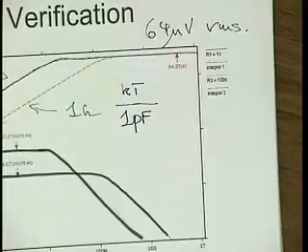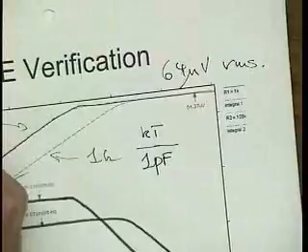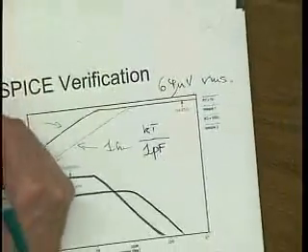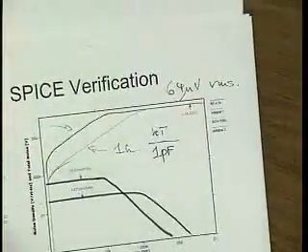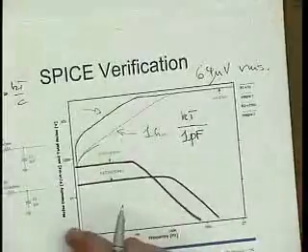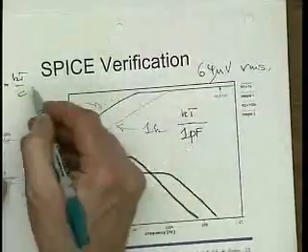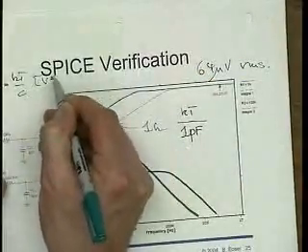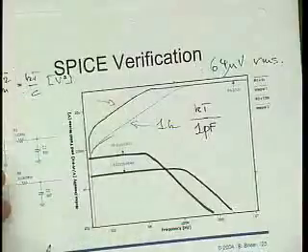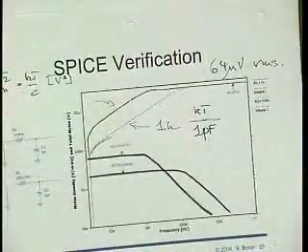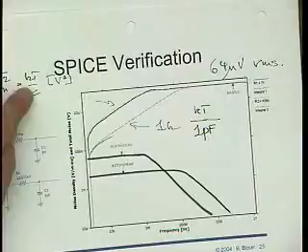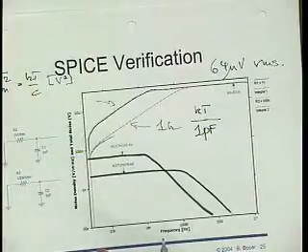I got you. You have to cut C by a factor of 4, and the reason is that the n square is kT on C, but here we plot the density in volts per root hertz, so just volts. This has units volt squared. So we took the square root of this, and consequently, if I want to get this down by a factor of 2, I need to get the square of it down by a factor of 4.